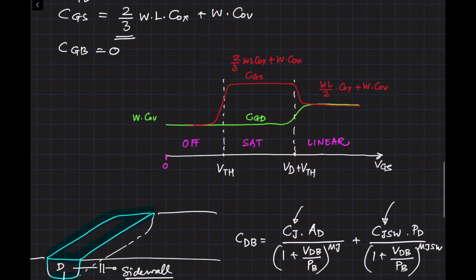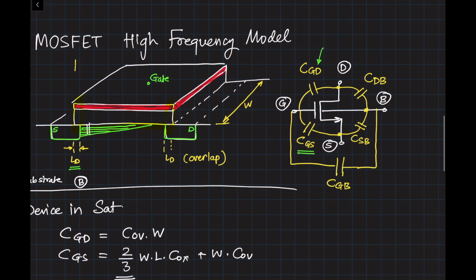For example, if for every transistor we are trying to evaluate we had to consider capacitance from every node to every node, then doing hand calculations would be a nightmare. So our job is to figure out which capacitances are important and only keep those in our analysis.